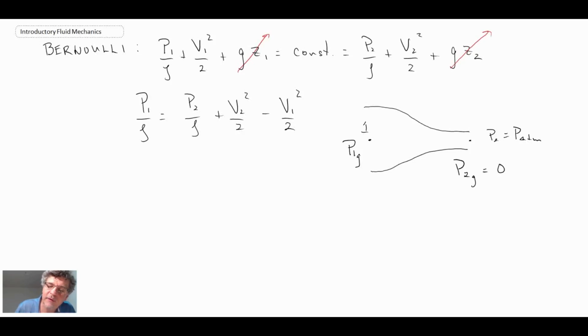And it turns out, just so that you're aware, whenever you have a free jet like we would have here, the pressure out here is atmospheric. Whenever you have a free jet, the pressure in there is also going to be atmospheric. And that's because a free shear flow or an interface cannot sustain a pressure gradient. Consequently, the pressure inside of this jet is going to be equal to the pressure outside. That's just an aside that is important whenever you're dealing with jet flows, but that's one thing that I'll point out there.